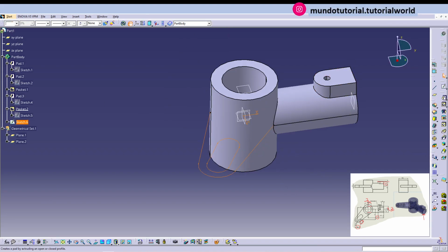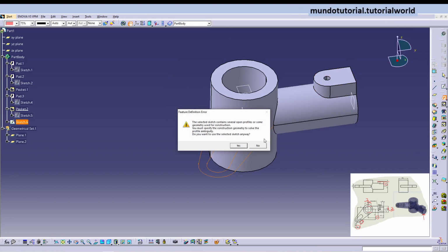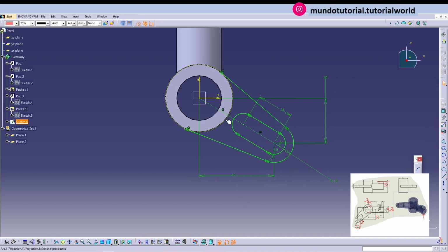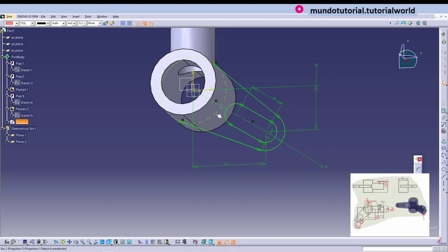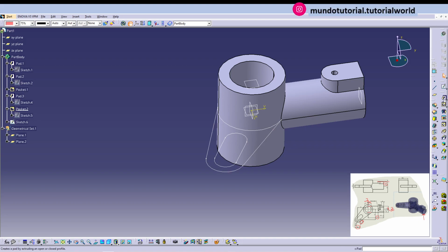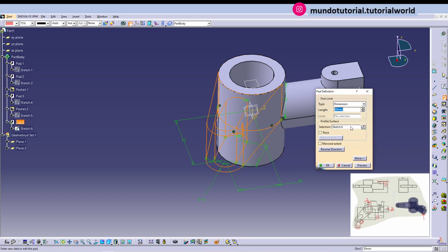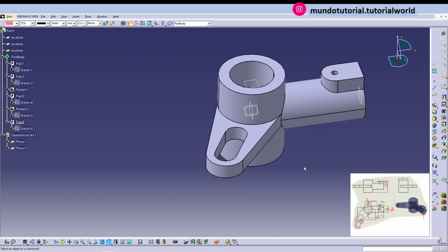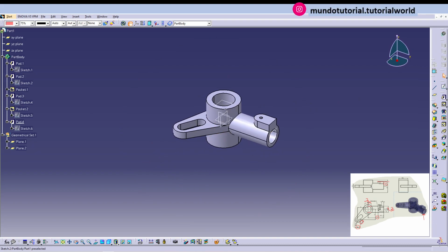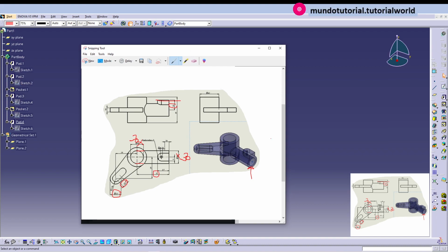And the total thickness here, oh, I have removed it completely. So let's edit again. I don't know, it shouldn't be, okay. It was as construction, so now it is better. And finally, if we pick this sketch, we have 10 millimeters in total, so 5 mirror extended, and that's it. This is the final geometry as we have in this model.